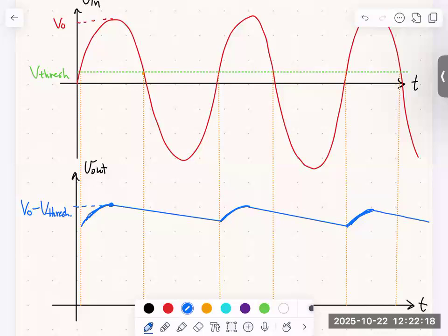And so this procedure just repeats over and over again. So I've drawn it here so that we can see this discharge of the capacitor. But if I make the RC time constant very long, then we can really suppress this so-called ripple. They call this change in voltage the ripple. And the longer I make my RC time constant, the smaller that ripple gets.